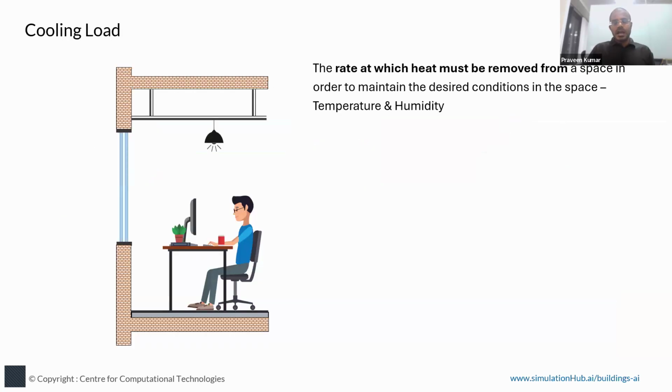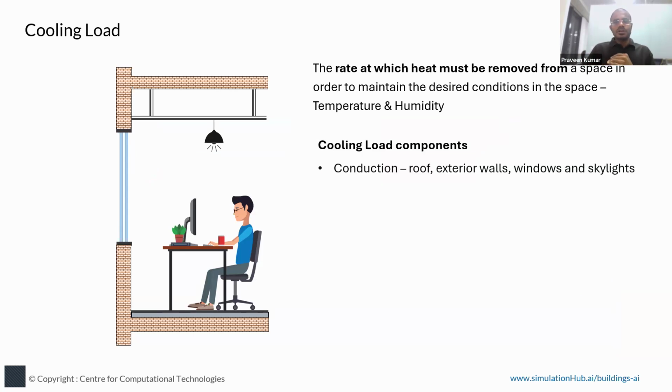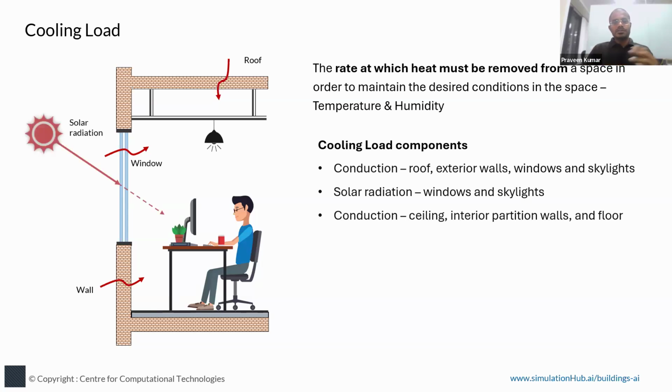And I'll start with the role of HVAC in modeling HVAC systems, specifically in load calculation as well as energy analysis. To understand that, we need to understand the different components of cooling loads. One is conduction from the roof, exterior walls and windows, the rate of heat entering the space through conduction, and solar radiation through window glasses, and conduction from ceiling, interior partition walls and floors.